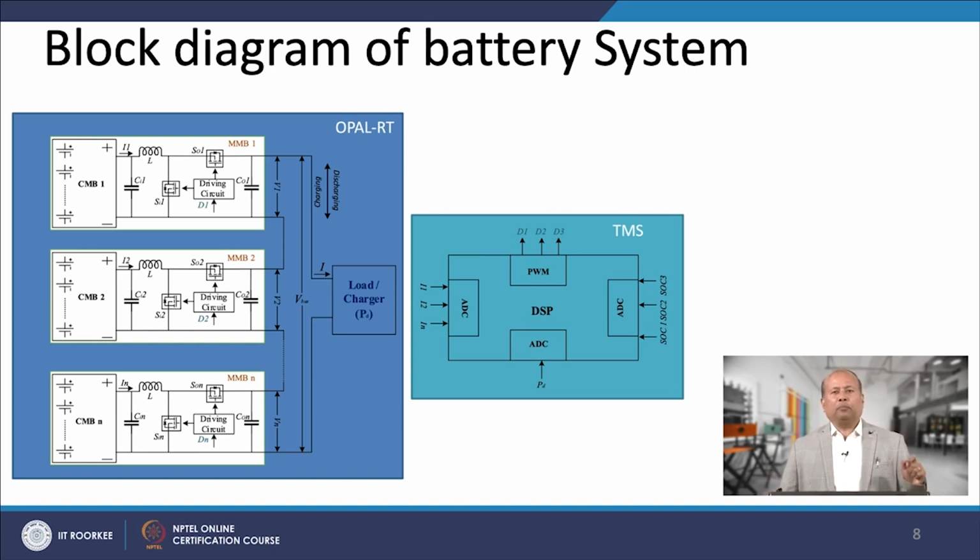To evaluate the proposed control algorithm, experimentation using a built-in MATLAB equivalent circuit model is developed. The simulated model consists of 3 battery modules and each module is connected to a bidirectional DC-DC boost buck converter for discharge and charge operation according to the reference current provided to it from the control algorithm.